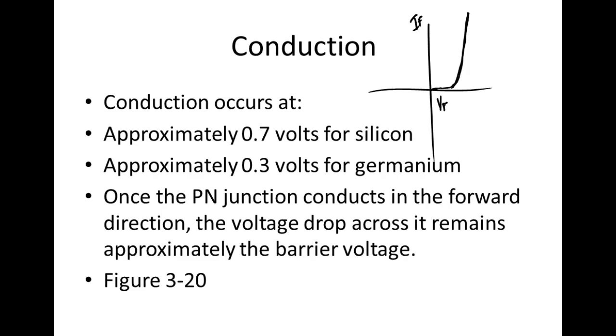You're going to take the diode, forward bias it, and put it in series with a resistor. What's nice about putting a resistor in series is you don't have to measure current; you can calculate it. You put your meter across the resistor, measure the voltage, and say I is equal to V over R, and then record that in a chart.